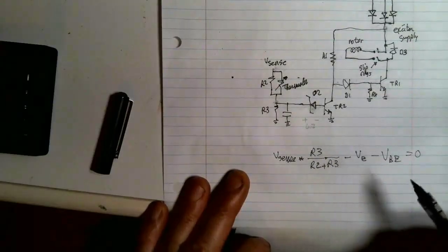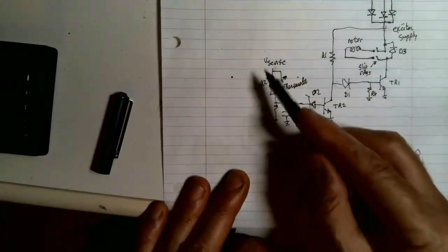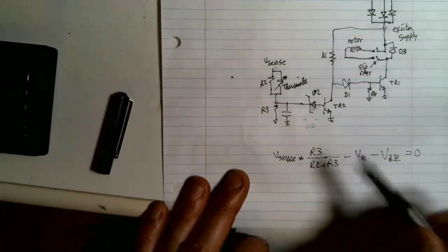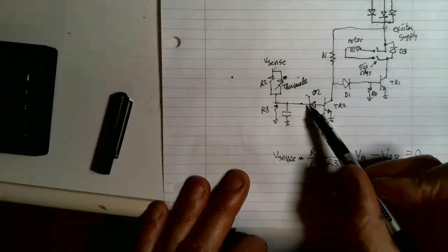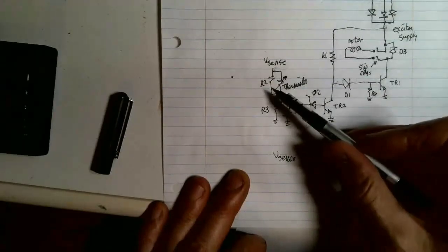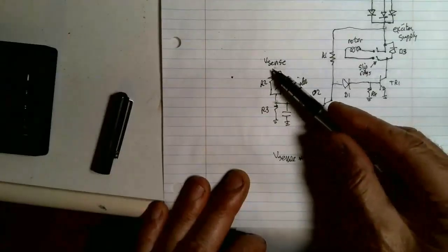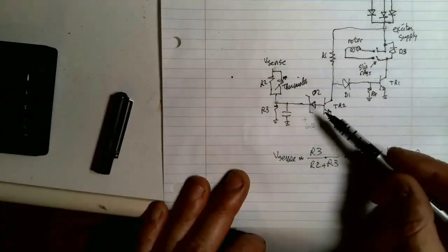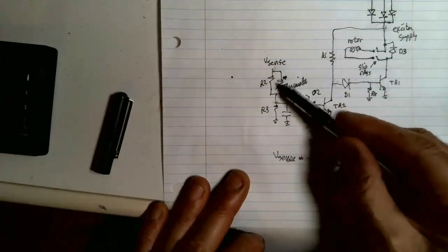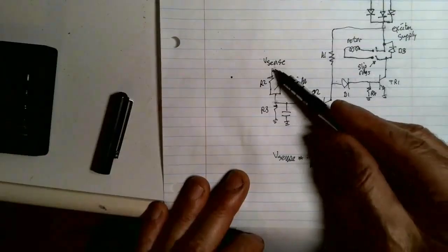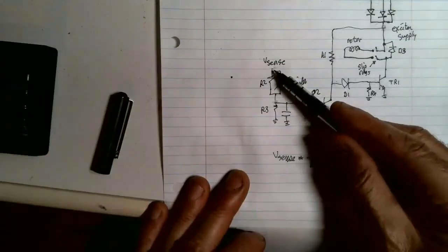So in that case, you could see that it's probably about what it is, because 0.7 plus 6.2 is 6.9, and then 6.9 times 2 would be 13.8 volts. That would then be where you would predict this circuit would start regulating if this was a 2-to-1 divider here, at 13.8 volts at room temperature.